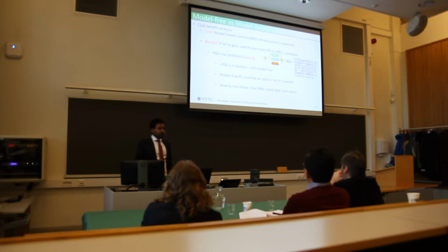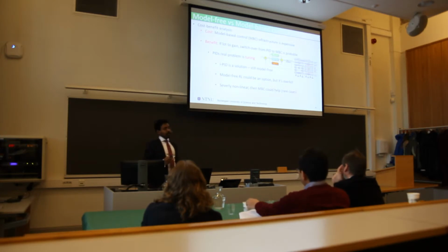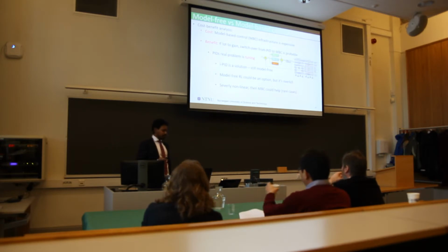But the PID's real problem is tuning, which can be addressed by intelligent PID solutions, which are still model-free, and it can also be addressed using model-free reinforcement learning, which is definitely an option, but it could be an overkill, but only time can show what it has. However, PID is known to function very badly in severely nonlinear systems, and there model-based control could definitely help, but it is again a rare case.